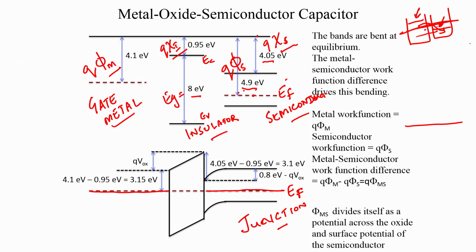But here is the question. So, for the Fermi levels to align, you need to have charge transfer. Like for example, in this case electrons are moved from the metal to the semiconductor, but you now have an insulator sitting in the middle. So, the question is, how did the charge transfer? Okay, so, there is something for you to think about. But let us just say that the charge did transfer and the Fermi levels have aligned, and this is a reasonably good assumption. Okay.